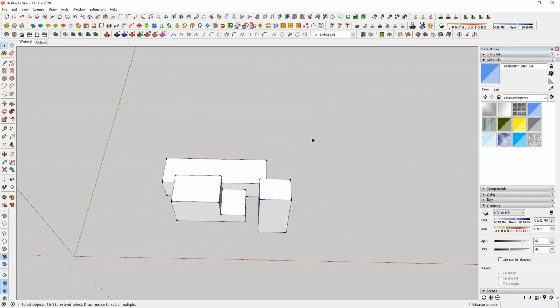Okay, so if you remember, we can create shadows and we can animate the shadows as well using the scenes and the animation tool. That is the scene transition. So for that, what I will do is first, let's pick the date. I will try to create the shadow range for the equinox again, 22-03, and I will try to find out the sunrise.